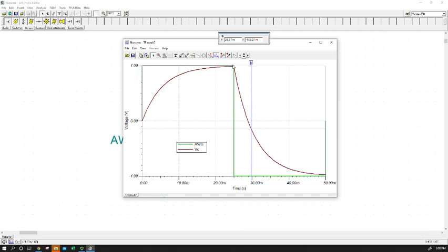Well, we're going to take a look at the voltage that would correspond to t equals tau. So again, I'll just run through that calculation for practice. I'm going to assume t equals tau. So the voltage drop over the capacitor should be my amplitude voltage, which is 1, times negative 1 plus 2 times the exponent function operating on negative 1, or e raised to the negative 1. So I can do 1 minus e, which gives me 0.367, times 2 minus 1, times 1, gives me negative 0.264 volts, or 264 millivolts.